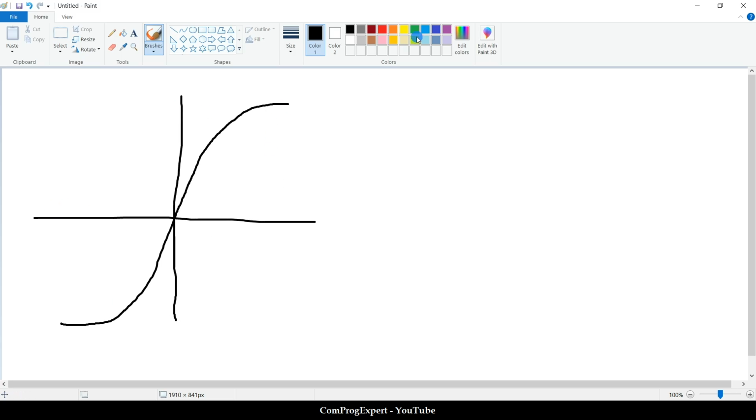We exported it from ANSYS Maxwell to MATLAB, and this is the load line. We can assume an arbitrary value for H. So we can write this error function. The input of the error function is H.